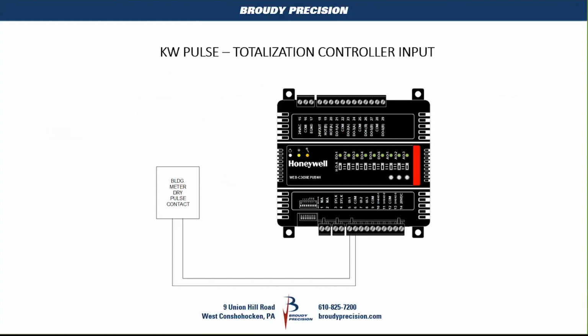As I said, in Philadelphia, PECO has a KYZ contact that they used to offer, and it told you every single pulse was equivalent to 1.2 kilowatt or 1 kilowatt. Let's make it real simple. So PECO would provide us with whatever was programmed at the meter, and every time a kilowatt was used, it gave us a dry contact.